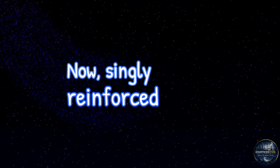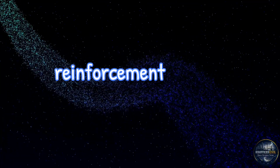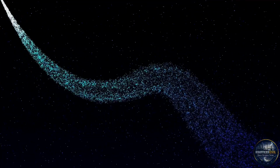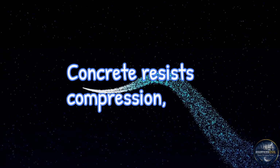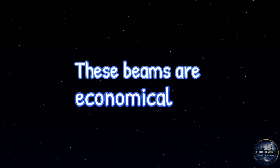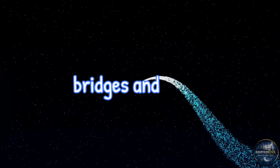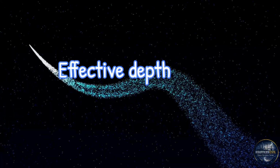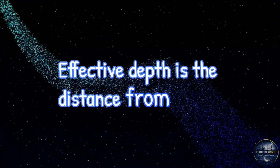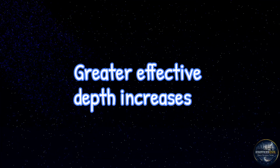Now, singly reinforced beam. A singly reinforced beam contains reinforcement only in tension zone. Concrete resists compression. Steel resists tension. These beams are economical and most commonly used in buildings, bridges, and slabs. Effective depth is the distance from compression face to centroid of tension reinforcement. Greater effective depth increases moment carrying capacity.